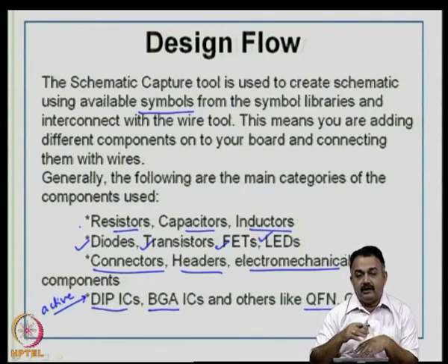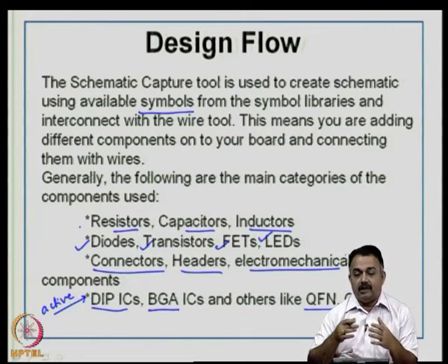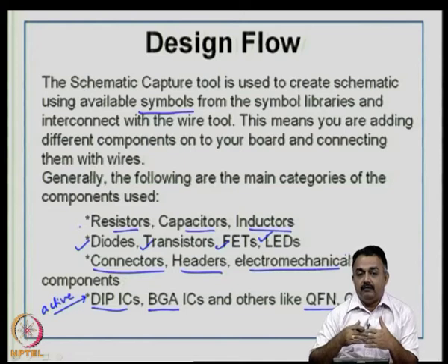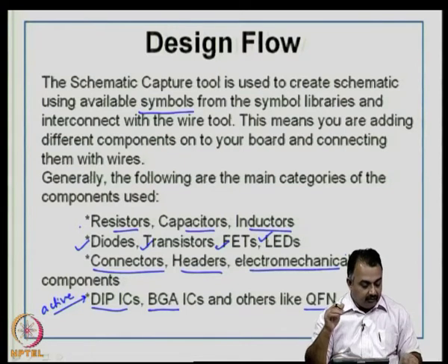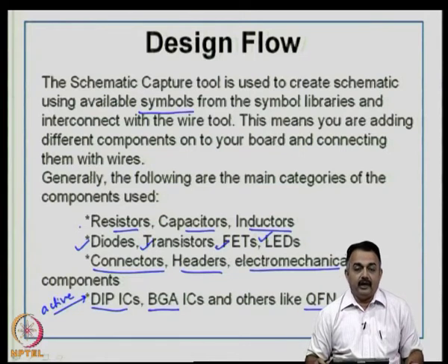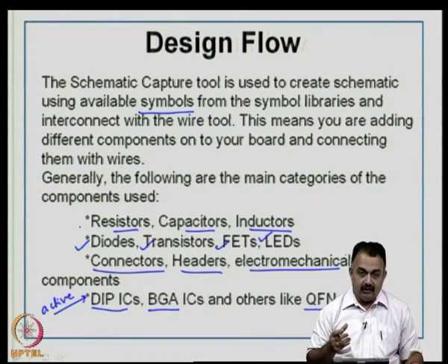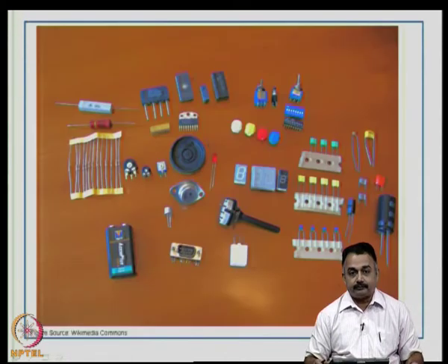So, you have to place connectors at the edges, and therefore, you have to carefully choose the exact location, because sometimes your board can be a daughter board which will get connected to a motherboard. Therefore, for connectors and electromechanical components you have to look at the issue of weight. Can it really be mounted on the board, or should it be outside the board area?